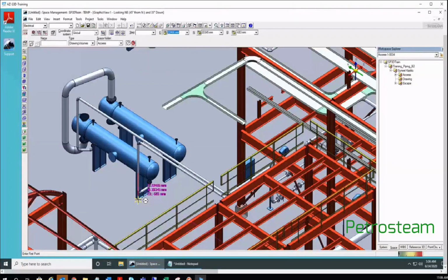So to cover this and cover some extra space, first point, as I told you, it should be. Now it is asking you to enter first point. As I told you, it should always be lower easting, lower northing, lower elevation. Okay. So to cover this exchanger plus piping fully, I have to reduce the easting value from 22,466. I will reduce it by 22 meters. And maybe that will cover the required point.